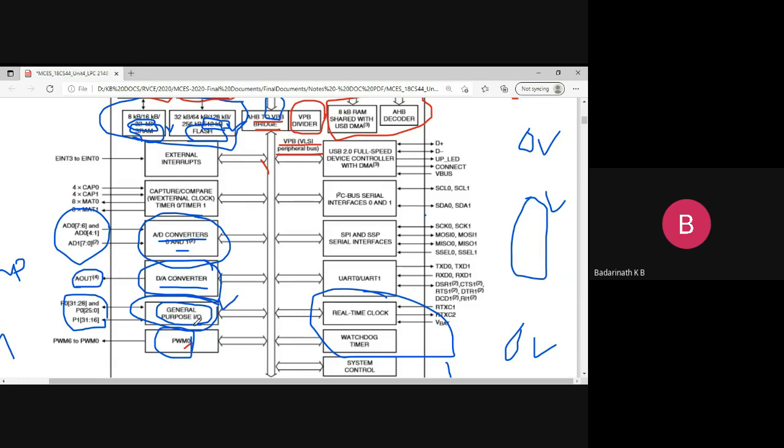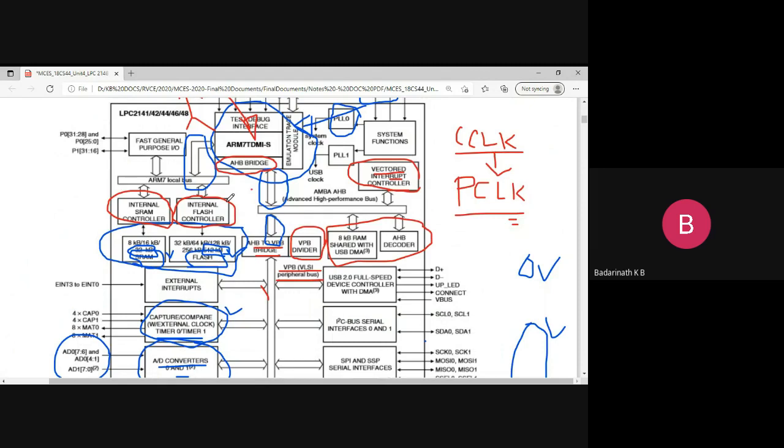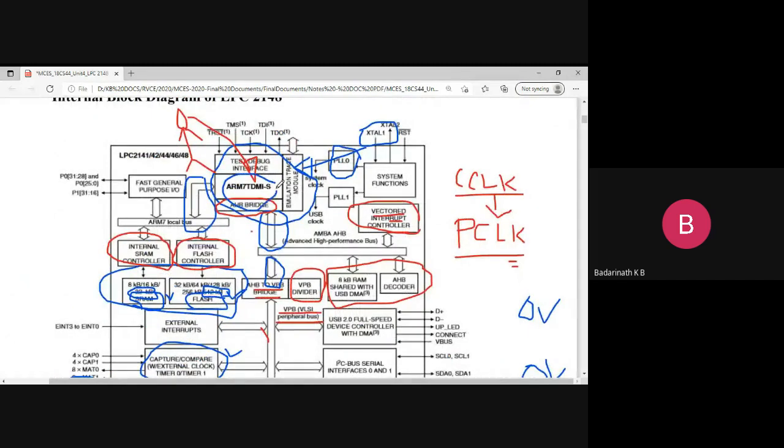So now we have studied the general purpose IO block, the ADC block, and the D2A converter. Now we'll go to another block. One of the very important blocks which any microcontroller generally provides, including your Arduino, is called timers. So what are timers? Timers are a hardware counting device. Whenever we want to produce 1 second, 2 seconds in a program, how do we do it? We write instructions in the ARM core and loop it many times. The loop produces repeated instruction execution that generates a delay.